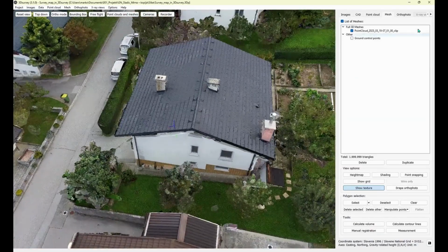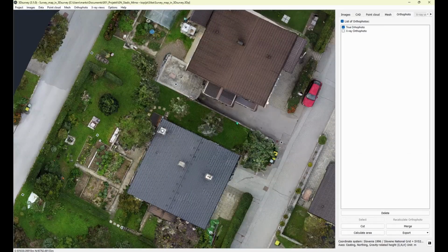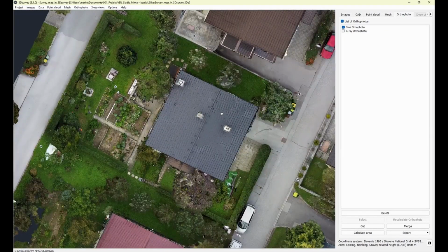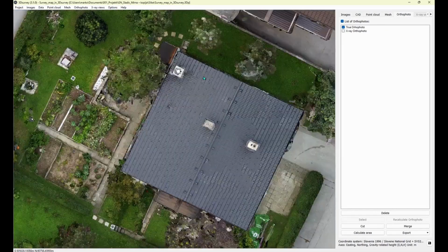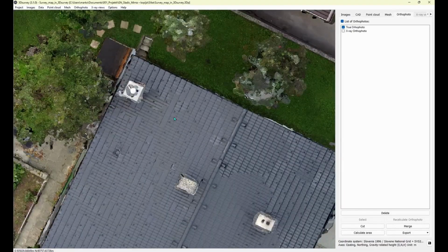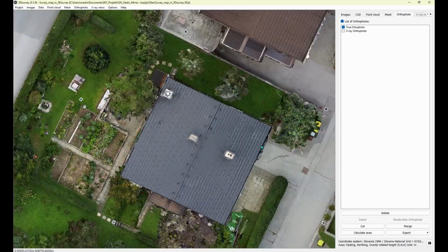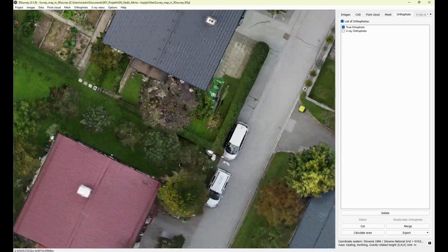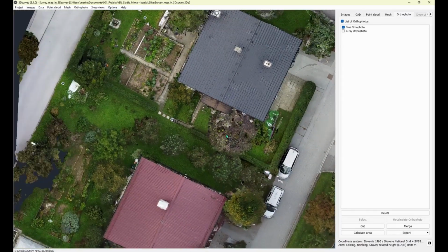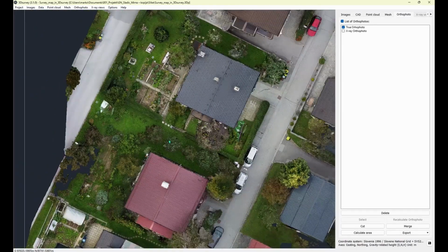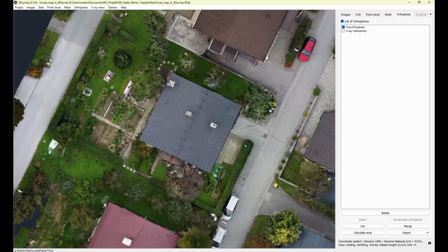And next result, the photo, because it was calculated from the full 3D mesh, it's also a true orthophoto, so it means the building roofs are in the right position, also all fences, traffic lights, or anything that's popping out from the terrain, it's in the right position.